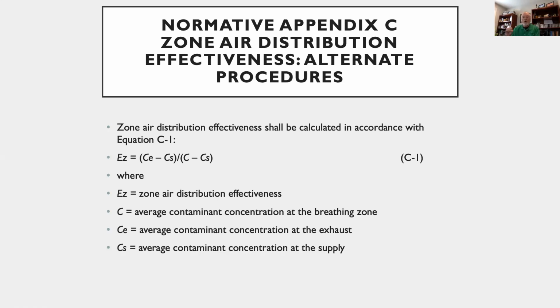It really is particles. So if you clean the particles out of the air through your system, it doesn't have to be all outdoor. It can be recirculated air that's highly cleaned. And highly clean for the particles we're worried about with COVID can be MERV 13. It doesn't have to be HEPA. It can be MERV 13. It's going to clean a lot, and so that's part of the challenge and opportunities for new design. How do we get the air to move? How do we get the cleaned air so we've got less exposure, less concentration in the breathing zone for the people that are in the room?